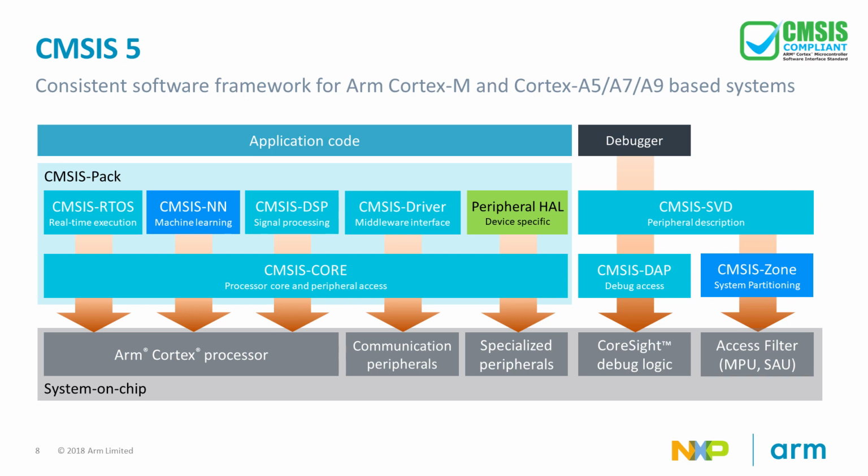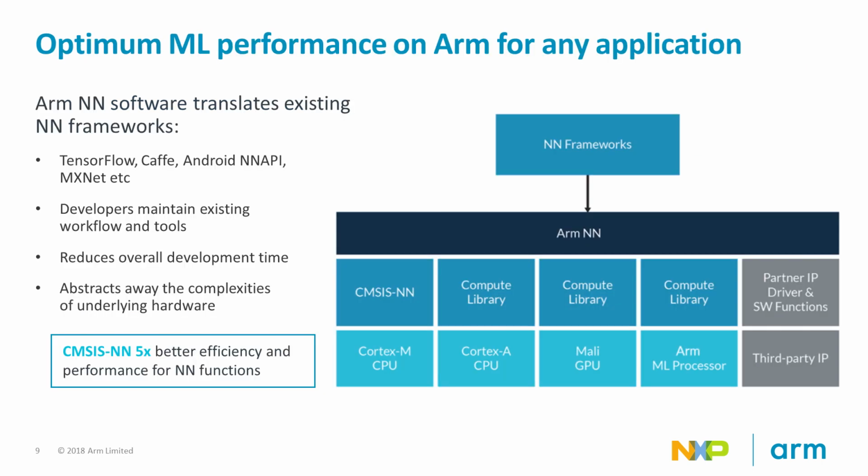The library includes functions that implement popular neural network layer types, such as convolution, fully connected, pooling, and activation. These functions can be used by the application code to implement the neural network that was pre-trained on a machine learning framework. The kernel API is also kept simple so that it can be easily retargeted from any machine learning framework that you use to develop the model.